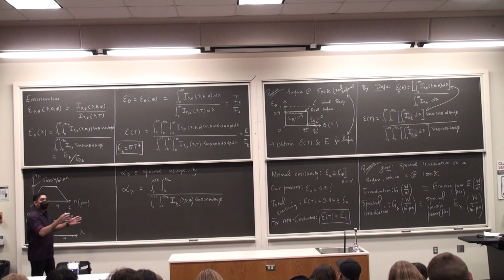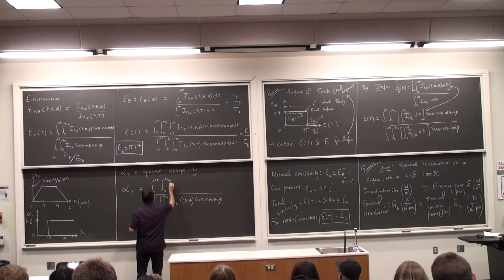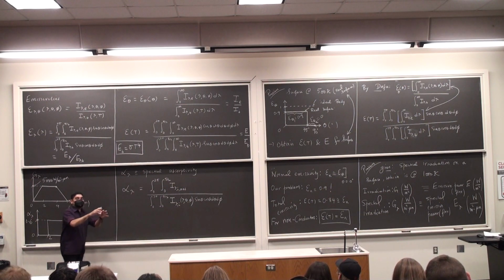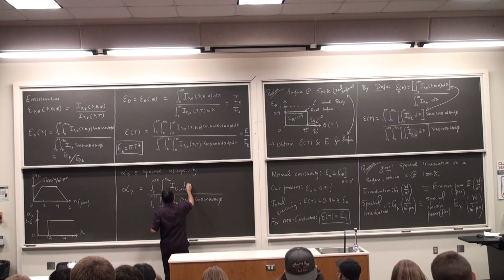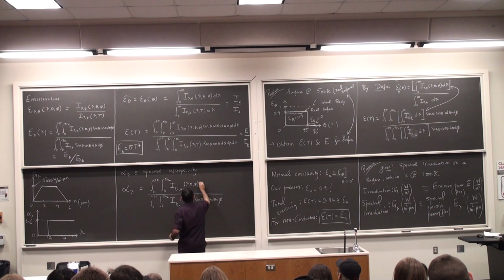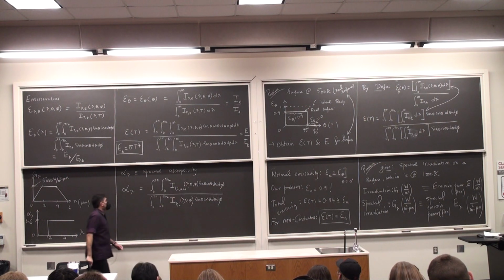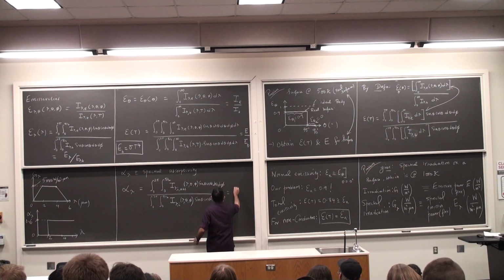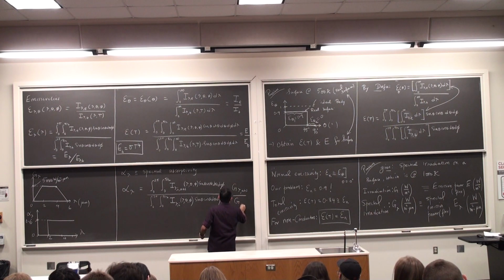This is the total incident radiation, out of which only a portion is absorbed. So in the numerator, I'm going to have the following: I lambda comma abs, whatever is the fraction of this incident radiation that is absorbed by the real body. Function once again of all of these: sine theta, cos theta, d theta, d phi. Excuse me. And this ratio is called G lambda absorbed by G lambda.